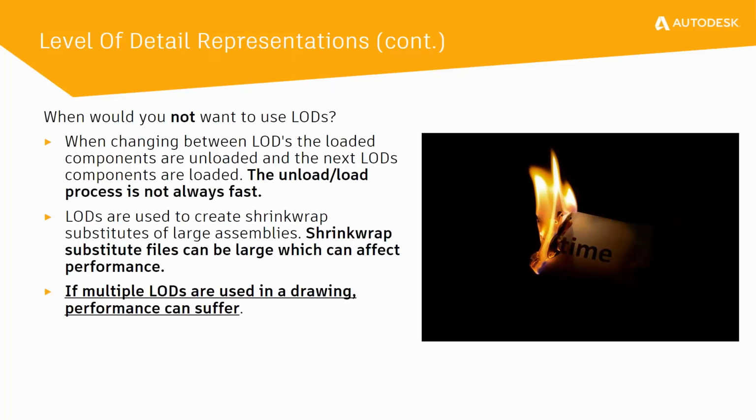If you're wanting to move from one representation to another, the requirement of an LOD means that it's unloading all of the components and then reloading the ones that are required, which is great because at any point in time you're not loading and maintaining all of the components like you would have with a design representation or a view rep. But the problem is the process associated with unloading and loading means that it takes time to transfer between one level of detail and the other.